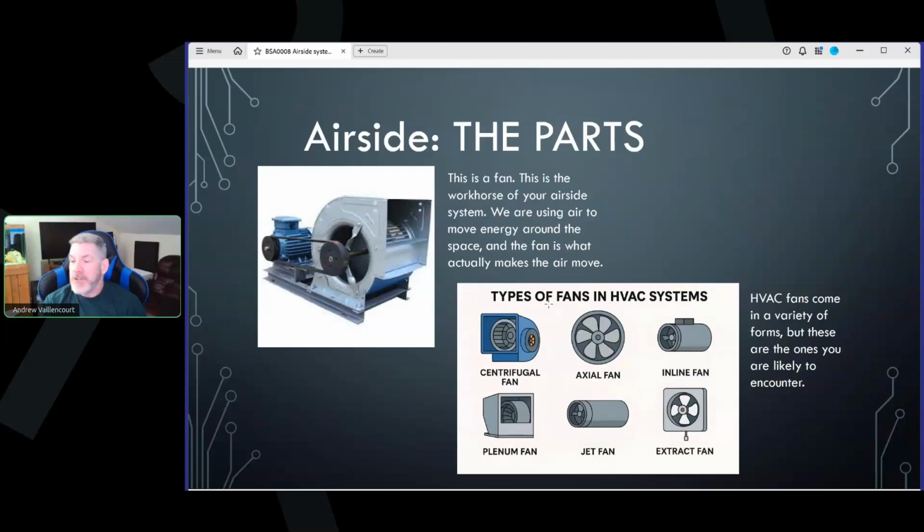In most HVAC systems, in, let's call it, a 100,000 square foot Class A commercial office building, your air handler is probably running 1 to 2 inches of static pressure. That would be average. I've seen them much higher though. I've seen 12-inch static in a hospital system.